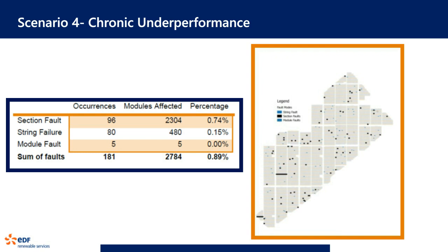As you can see, when we took the results of all of the aerial IR imagery and overlaid those with precise locations from an as-built drawing, the pattern you see is that, frankly, there is no obvious pattern. These problems are spread throughout the plant, which reinforces what I was saying earlier about the difficulty in finding this type of problem through an inverter-to-inverter analysis, because, as you can see here, virtually every inverter was impacted almost the same amount, to about the tune of that 1%. So, in doing this, one of the wonderful things about the aerial thermography is that it can actually tell you the type of problems.